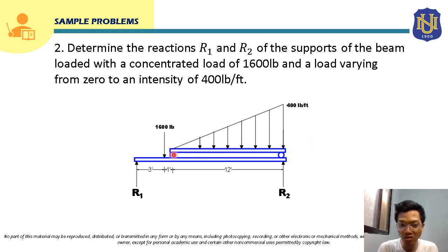We will solve for its reaction force due to this applied load, and after that, the reaction force that we solve from the free body diagram of this upper beam, we are going to transfer to the lower beam, with opposite direction, because this lower beam actually carries this upper beam.